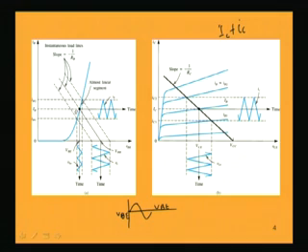Now, the intersecting point between this load line and the characteristic for a particular base current at which the transistor is being operated is given by this point, which is known as the Q point, that is the operating point. This operating point is the DC point. That means we are not applying any signal. What will be the collector current and collector to emitter voltage is given by the Q point, or quiescent point.